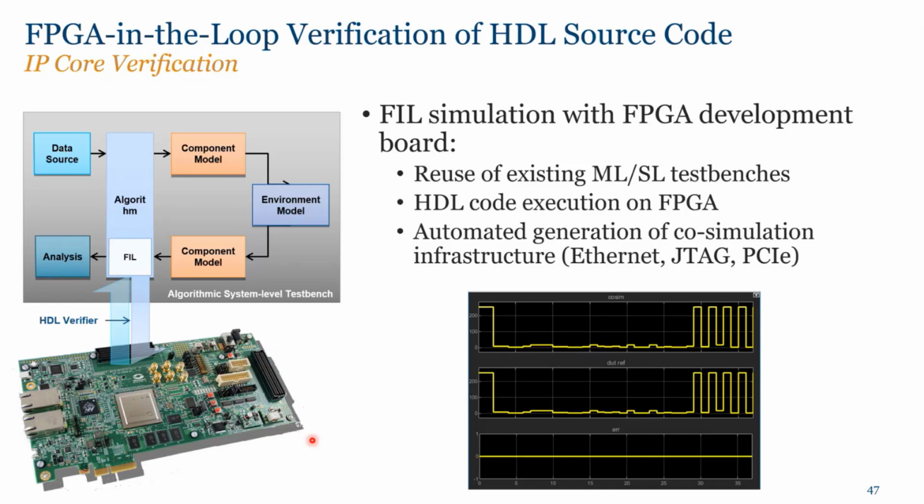We have a structure that is implemented directly on the FPGA that will be responsible for synchronization between Simulink or MATLAB and your FPGA. Of course, you can achieve the link between the FPGA and Simulink through Ethernet, JTAG, and PCI Express. For that you will need a hardware support package that we can provide freely with our tools, and we usually support the development boards that are very used on the market today.